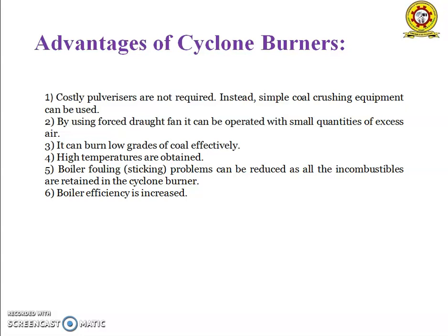Another type is the cyclone fired boiler. In cyclone fired boilers, the furnaces are arranged as horizontal cylinders. The pulverized fuel is fed along the periphery of the cylinder. The hot gases travel axially into the water tube section in a tight helix path. The temperature generated in the combustion zone is quite high, and because of this the tubes are coated with fused ash, which goes on collecting the ash particles in the flue gases. The outgoing gases contain particles of less than 20 microns.